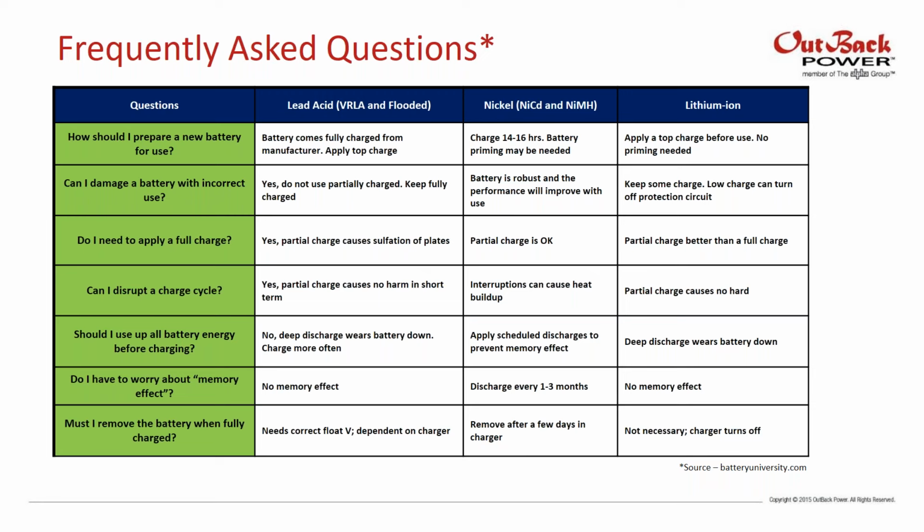So this one's a little odd. Do I have to worry about memory effect? It's almost not relevant to our conversation. The memory effect only affects specific nickel-cadmium batteries. And just to refresh everybody's memory, it's an apparent symptom that the battery remembers the point in its charge cycle where charging began and during subsequent use suffers a sudden drop in voltage at that point, as if the battery had been discharged. So again, it only applies to specific nickel-cadmium batteries, and they're not the batteries that we use with renewable energy storage. So if somebody asks you about it, tell them it's not relevant.